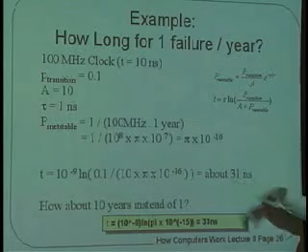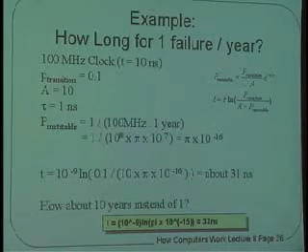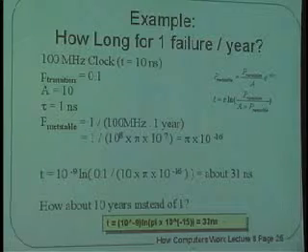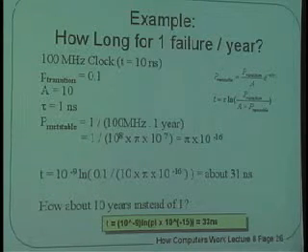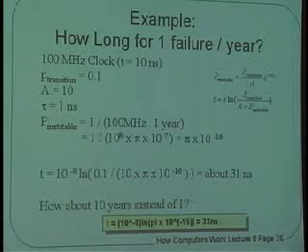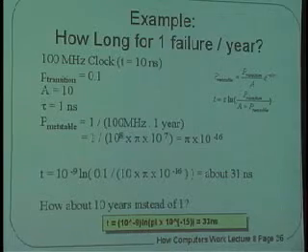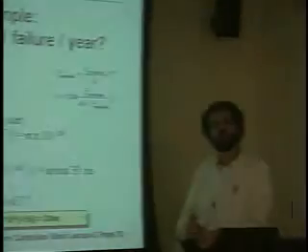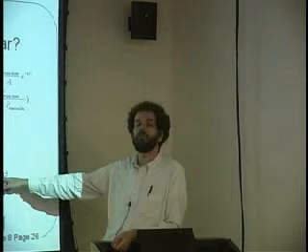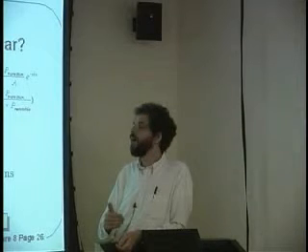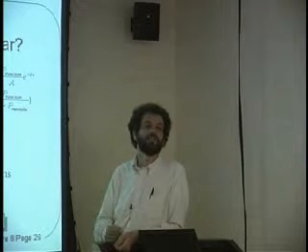And the answer is around 31 nanoseconds. That's 31 billionths of a second. So if we feed this asynchronous input to the flip-flop, and we do it 100 million times a second, and we're willing for it to not have come up with the answer once a year, then if we only wait 31 billionths of a second after we give it the problem, it will come up with the answer every time except once per year. And once per year, it'll take longer.